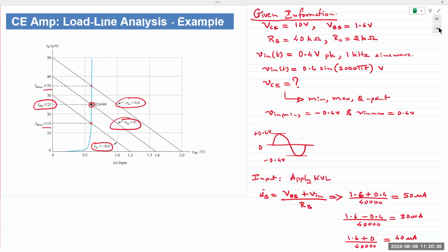But let's say you take the exact same transistor as we have here. Right now, the beta value is 100. The other transistor has a beta value of 200. What would happen? Your Q point would now shift. And when it shifts, it could drive the transistor into saturation at one end, or it could drive it into cutoff. The exact same circuit with the exact same DC biasing voltages would not work exactly the same for different transistors. And that is the biggest drawback of this circuit.